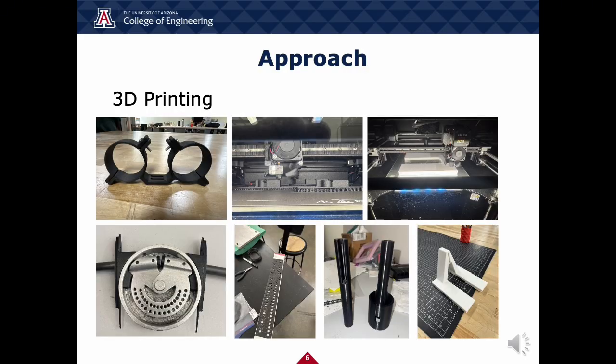3D printing let us rapidly design, test, and iterate custom parts that would have been slower and more expensive to machine conventionally. We used PLA for quick non-structural parts and jigs, nylon PA 612 CF15 for high-strength, lightweight structural components, and aluminum magnesium SLM for the wing box, where we needed high strength without the delamination tendencies seen in nylon CF. This gave us a fast, material-specific workflow that allowed us to quickly adapt and refine our designs as needed.